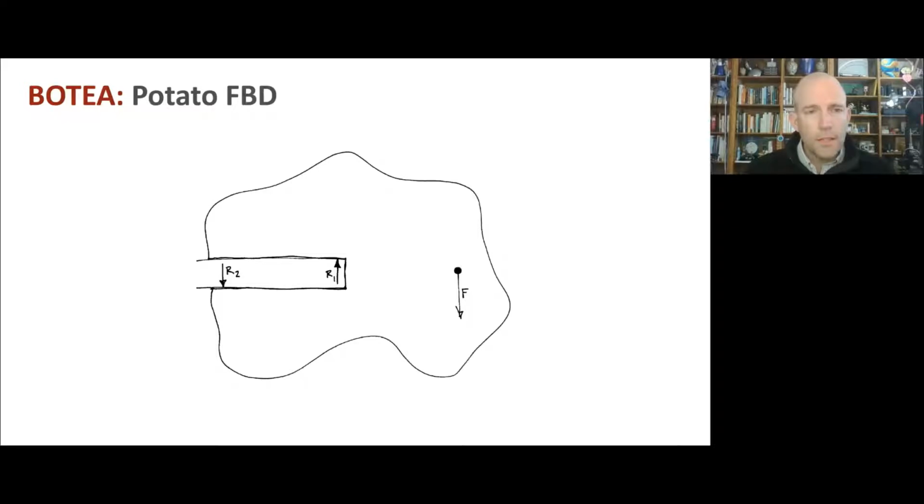All right. So now we've got kind of a free body diagram for this really generic design, this potato design. We can also learn some other things about it. One thing is that this material up here in the upper left isn't really doing much for us. It's not carrying its weight. We don't want a reaction force over here. If R1 were way over here, that would be bad, right? We'd get a much bigger lever arm for F and a smaller lever arm for R2. Not good. So we want R1 to be over here, and we don't need all of this stuff.